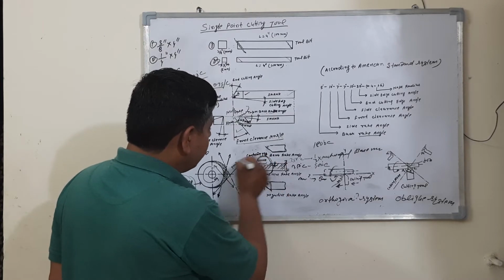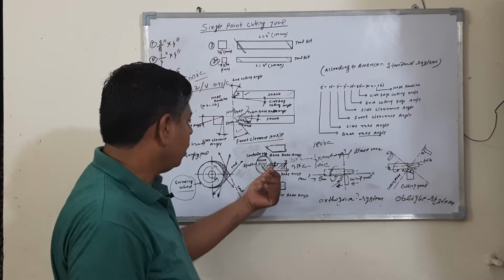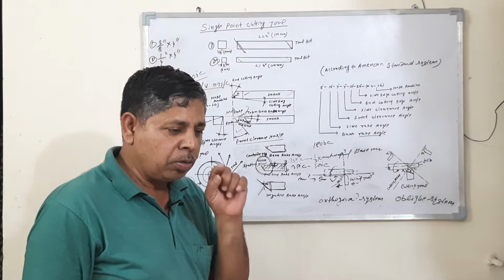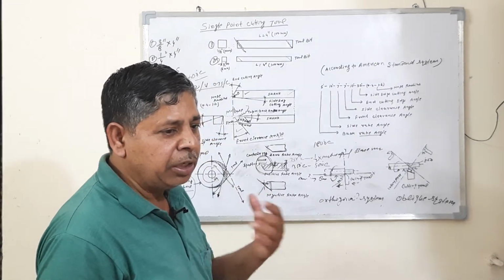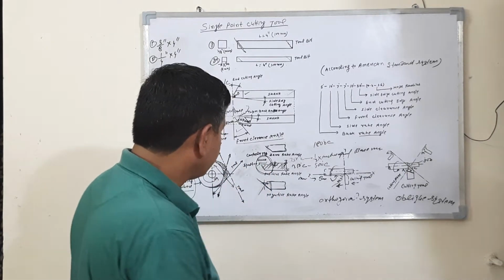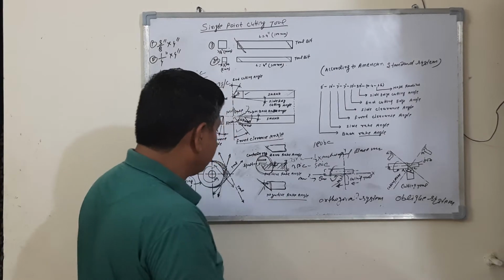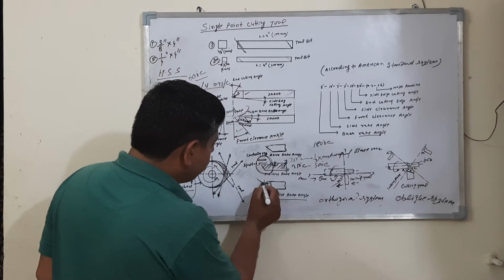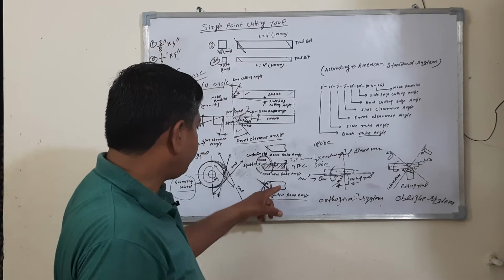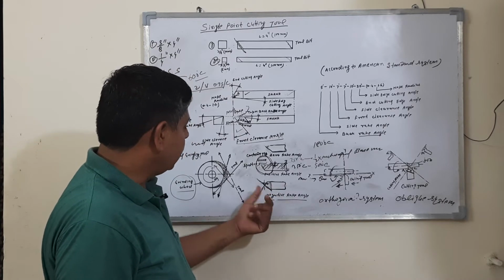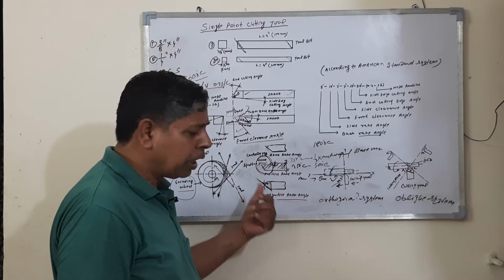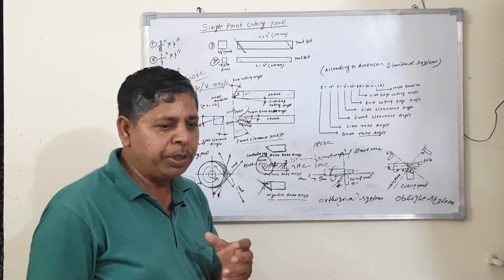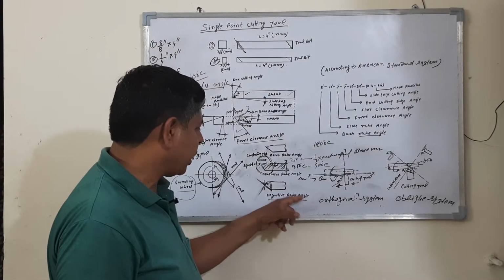This process is complete. This type of brazed tool is used for mass production for a long time, and gives a high depth of cut and good finishing on the workpiece. This is the negative rake angle. So negative rake angle on this, this is the tool slope on a tool bit. This type of tool is used for very high depth, low speed, but you cannot get good finishing of the workpiece with negative rake angle tools.